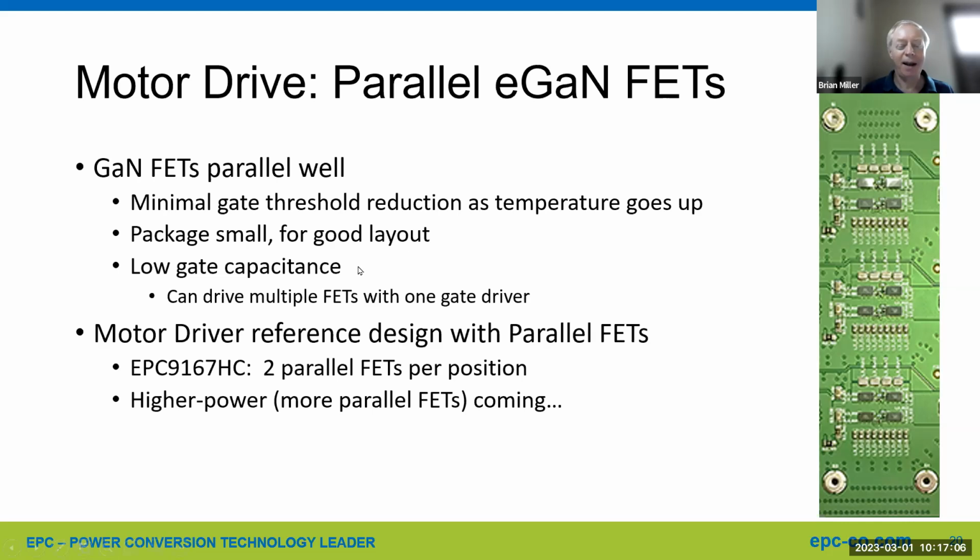And also, the gate capacitance on GaN FETs is very low. And what that means is you can take one gate driver and drive multiple FETs with one gate driver. By multiple, 4 has been done quite commonly, and more is possible with some design trade-offs, but that's possible also.